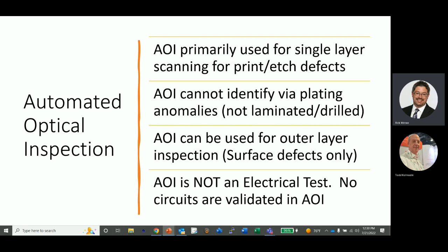But when you go through the plating process, in many cases you could have some small discolorations here and there, or the copper is a little bit shinier in different places. AOI is an optical machine. It's an automated optical inspection machine that takes a camera and looks at a panel. In this case, it's looking for copper.